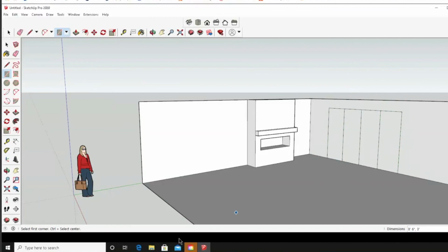It offsets, in this example, either in or out, the same shape with the measurement that you want. So on the bottom of page 7, you're going to use the offset to offset each frame, and we're going to offset it inward 2 inches. So we select the offset tool. And now I'm having to figure out which one it is. There it is. It's this one.